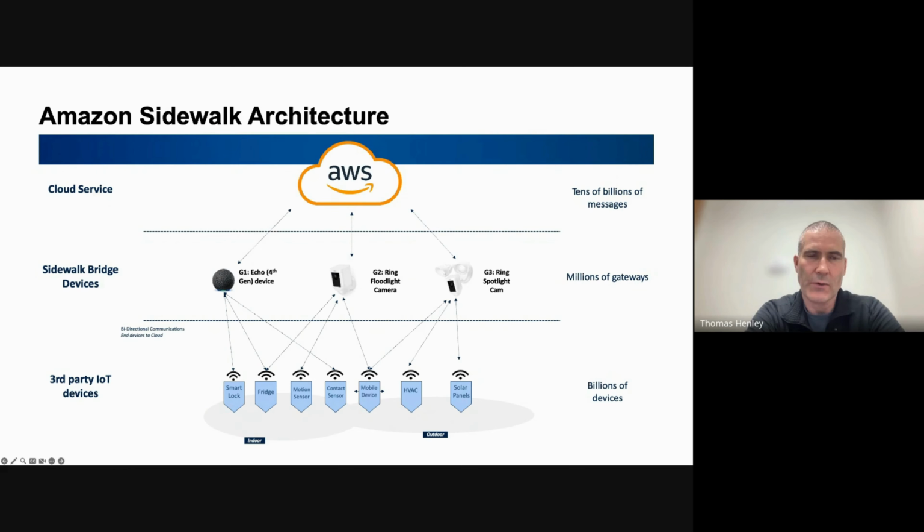This is suitable for devices that tend to be around people's homes or businesses where the gateways are and close by to those gateways. As a medium range, medium rate protocol on the sub-gigahertz band, we support what we call sub-gigahertz FSK. So this is a sub-gig protocol that gives range of maybe 150 to 200 meters. And as I mentioned, it's a medium rate protocol.